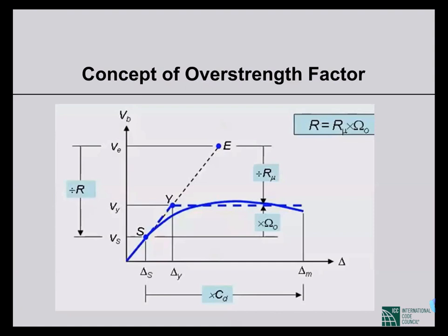In that case, the energy that our structure could sustain, the amount of energy, the same amount of energy it could sustain in the elastic case, in reduced load V if the base shear were Vy, and if our structure could undergo deformation up to delta M, so possibly the same amount of energy it could sustain. So that is the concept of inelastic design.